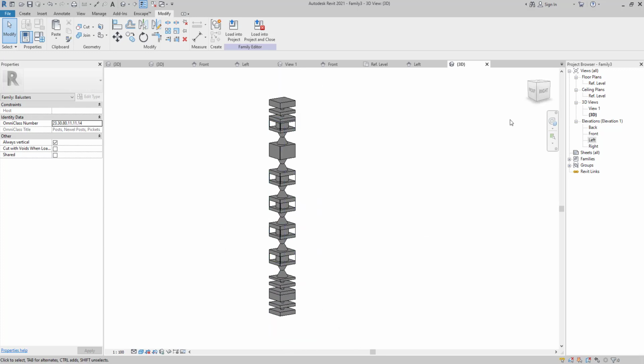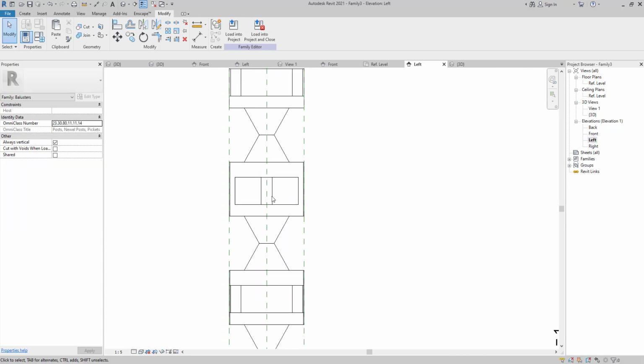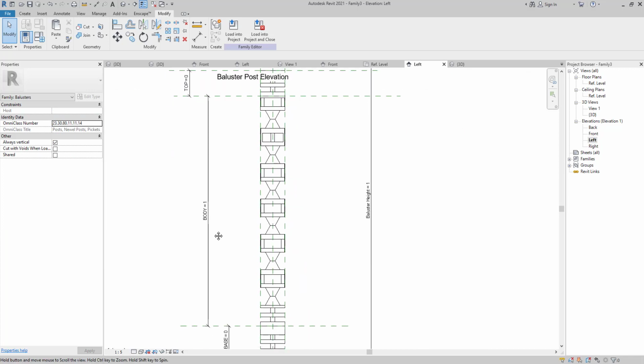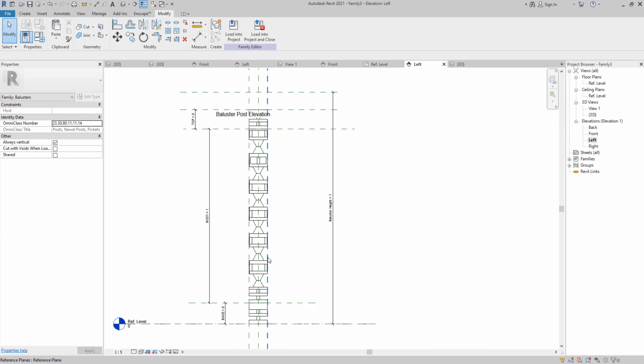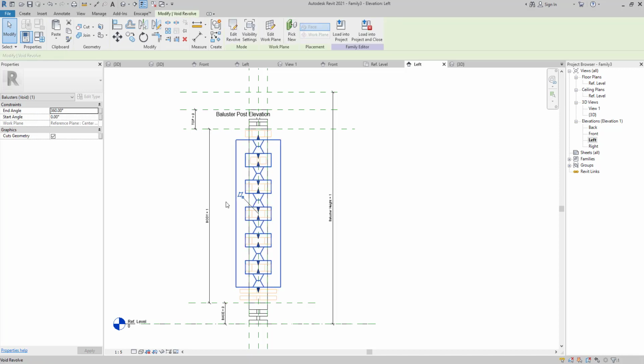The next step, so we will review what was important here. We created our top, base and body. The dimension is alright. We can change it from the length. We can change it with the width from the top view, but we need to also consider how open we are going to create our void element. If for example you create your length bigger than your void, you need to consider that it's not going to support it, or it's going to change the shape of your design.